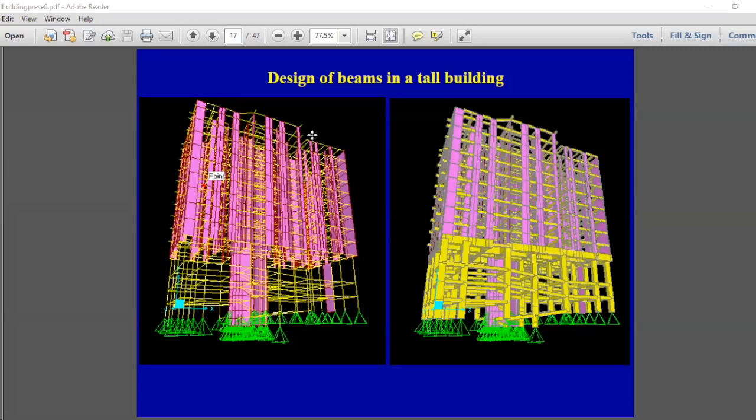Then the structure contains shear walls arranged in the upper levels of the structure, so that the whole structure can be constructed with car parking in the lower levels and the apartments in the upper levels. But if you look at the shear core, you can see the core is continuous, because the core used in the car park levels is used at the upper levels as well.